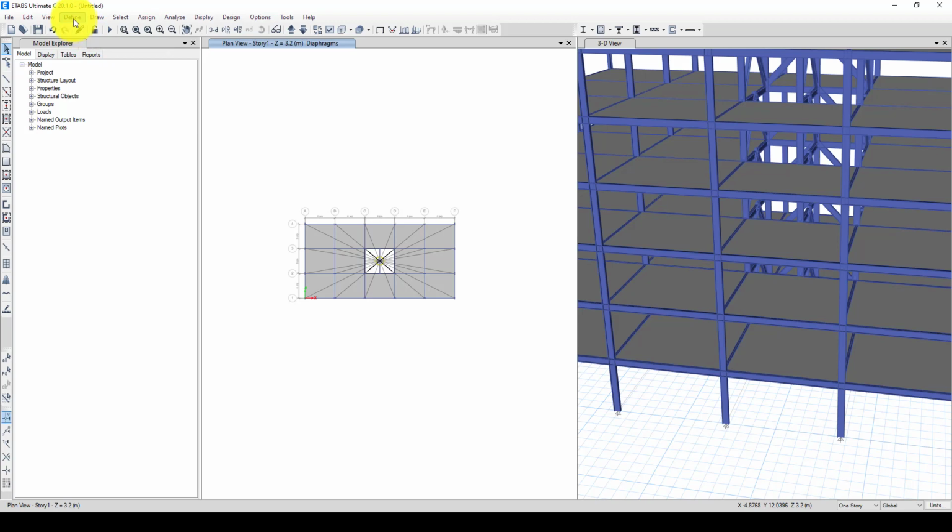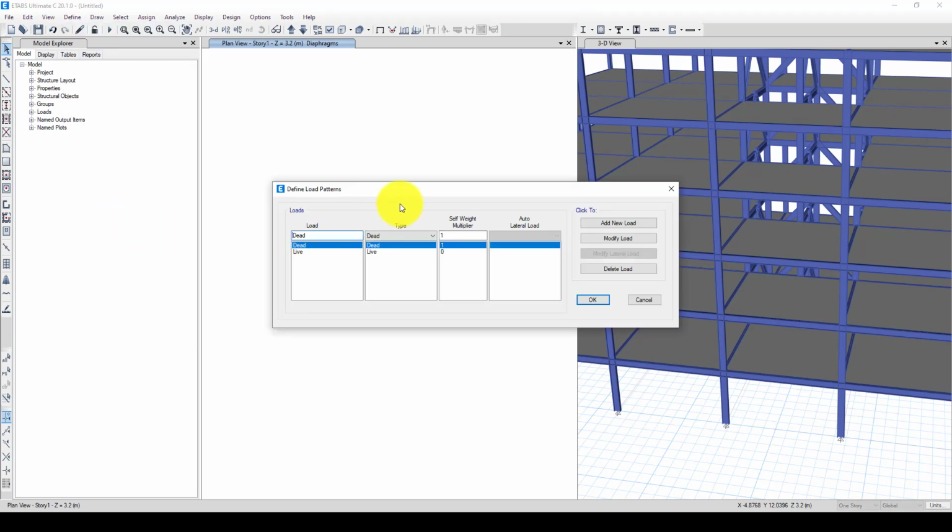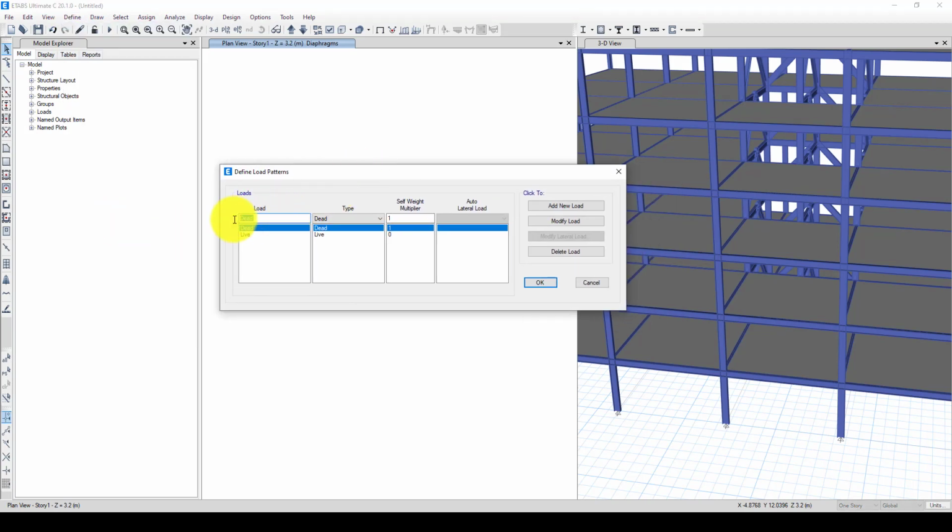point. Now we go back to the load pattern, and here I'm going to define EX, which is earthquake impacts on the X direction, seismic, and using ASCE 7-16, which is the latest version of that one, and again in the Y direction. So the program, for the combination for the design part, will consider the minus and positive. So we can define just 2, that is enough.